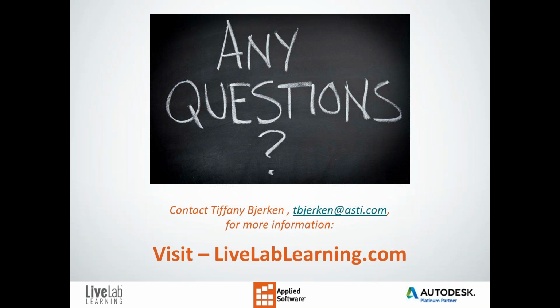So ClearEdge 3D is one of them, and there's another program out there which I recently spoke to someone about at one of our events a couple of weeks ago at BIM and Beer, and it's called Qubit. I looked at Qubit many years ago, and at that time it was focused on CAD, but now, this gentleman that I spoke to showed it to me on his laptop. When you bring in the point cloud, it also has the image right next to it. So if I want to trace the point cloud, I can click on, let's say, the corners of my wall in the photo, and it knows where the corner of the wall in the photo is in relation to my point cloud. So it seemed like a very good workflow for at least placing walls. I don't know how their MEP side works. I have not seen that.